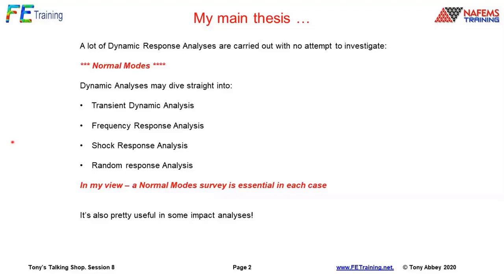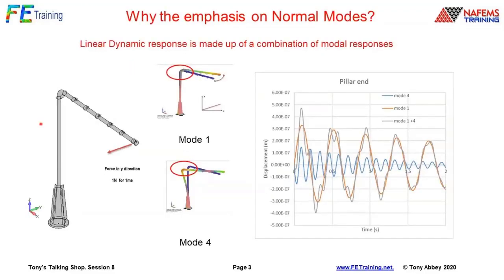So I'm saying that if we do any kind of dynamic response analysis, we should be doing a normal modes analysis to understand what's going on there. So why the emphasis on normal modes? Well, we're doing linear dynamic response, and the mathematics, the simulation, of linear dynamic response is made up of a combination of modal responses. And in nature, as long as the displacements are small, we could argue the same thing. It's going to be a modal combination.